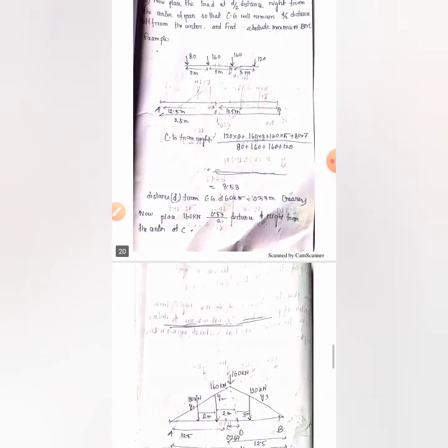Keep the 160 kilonewton at the right section from section C, 0.53 divided by 2 meter away from section C. Now automatically the center of gravity will remain 0.53 divided by 2 meter away from section C on the left. In other words, the center of the span is in the middle, in between the 160 kilonewton load, under which we will get absolute maximum bending moment, and the center of gravity. So it is followed, and then we have to place these loads like that.